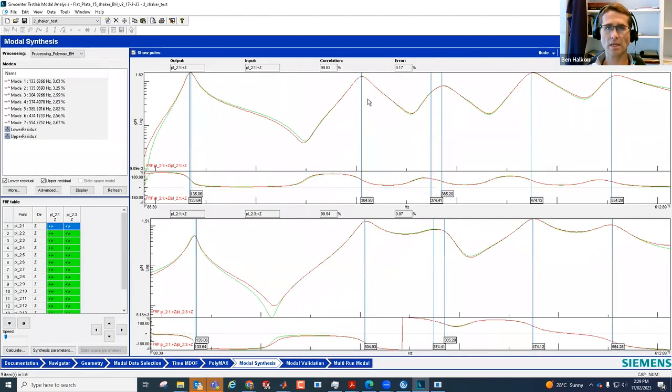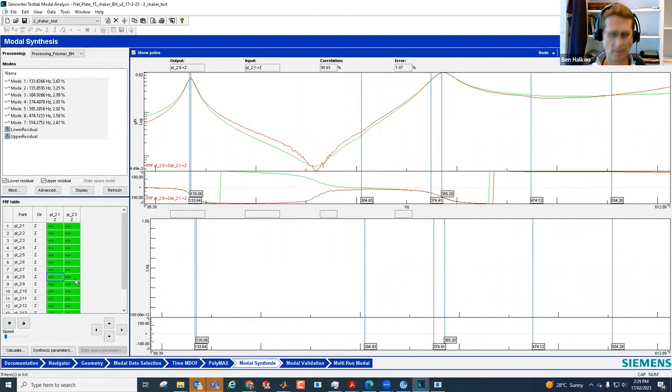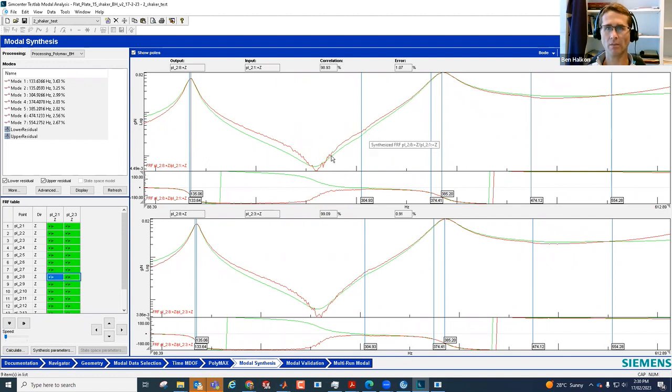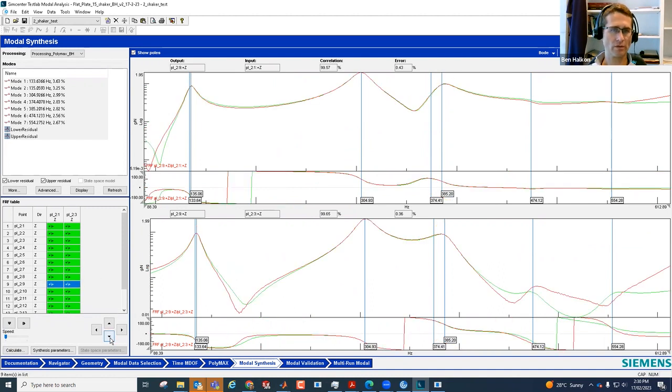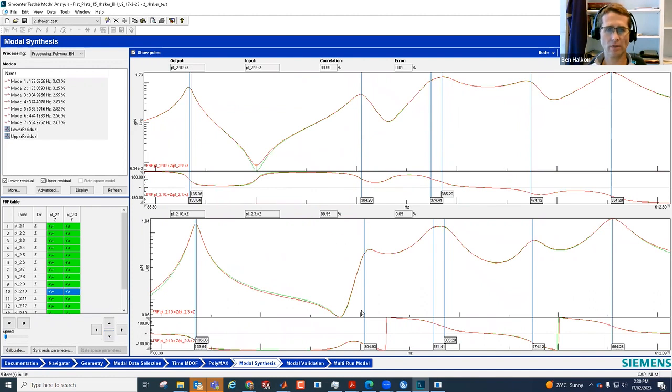Yeah, we can see here, let's change back to those two, that there's very little motion here. And the noise here is quite high. Of course, our mathematical model doesn't include the noise, and that makes it easy for us to differentiate. The green curve is the mathematical fit, the red curve is the data, and there's some relatively high noise, but we're really focused on these resonant frequency locations. Okay, so we keep scrolling through, keeping an eye on these things. Let's have a look at some other features.